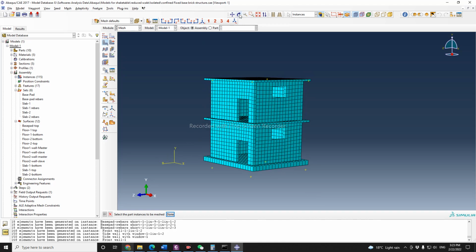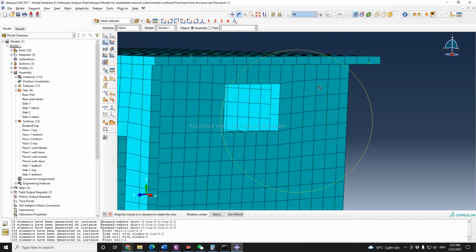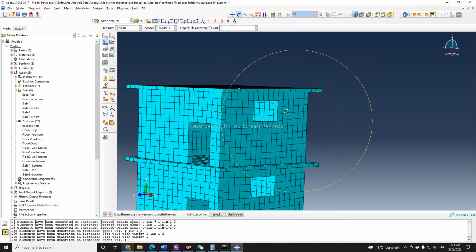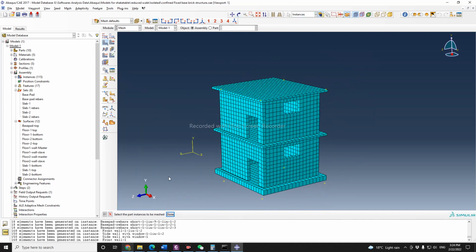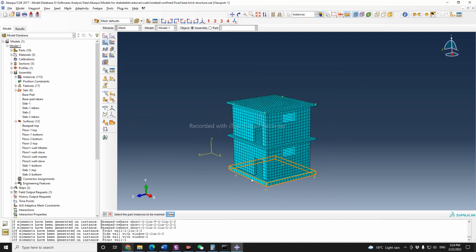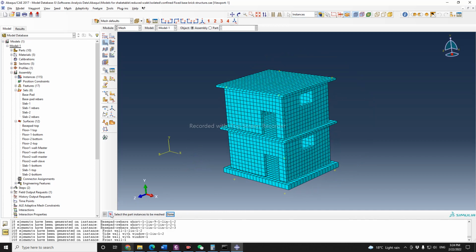Alright, so we might have some curvature over here. That's just the beginning. You need to play with the mesh until you get an accurate result. Actually, there is a study which is called mesh convergence analysis. You need to do that convergence analysis to exactly know the dimensions of your mesh. By convergence analysis, I mean that you need to vary the size of your mesh and then identify the results, and then vary your mesh and then identify your results.